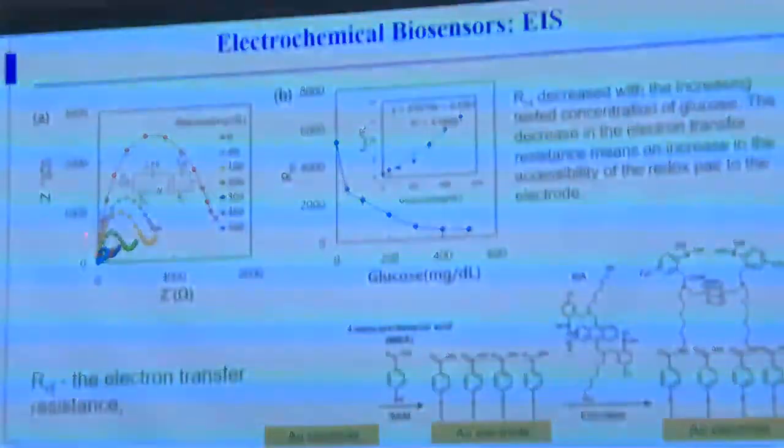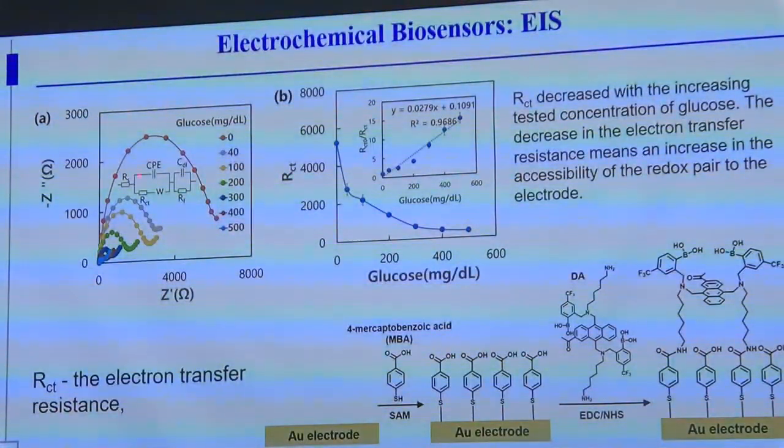But in a very, very simple way, you have an ideal impedance spectroscopy graph. So for example here, that's the semicircle here, and this is the corresponding Randles circuit here. When impedance starts, how far it is from zero in the high frequency range, that point will give you the solution resistance.